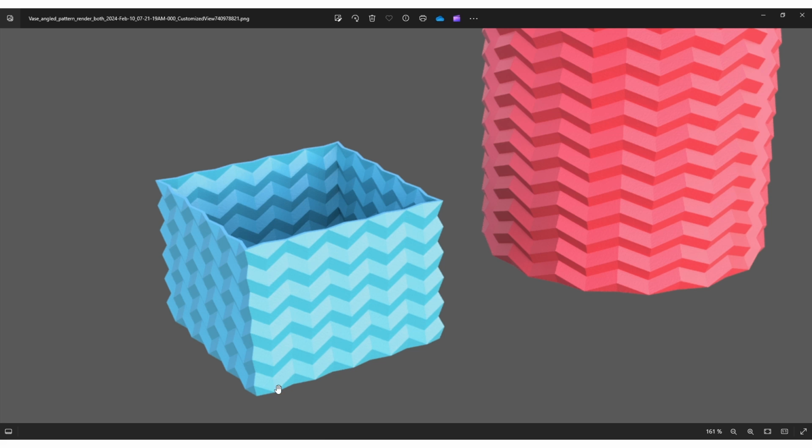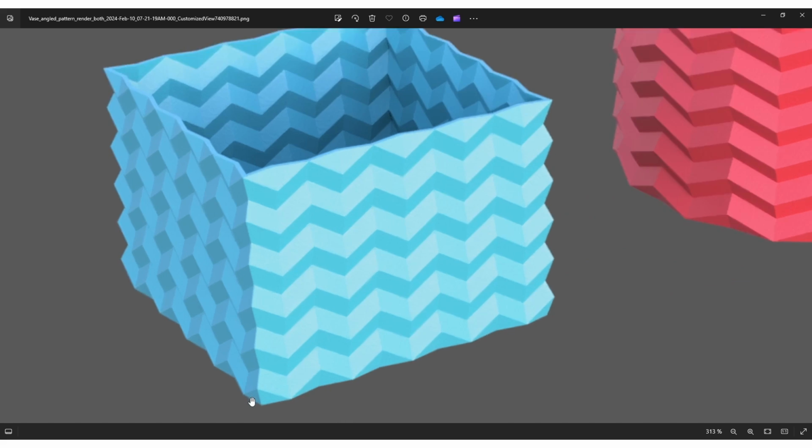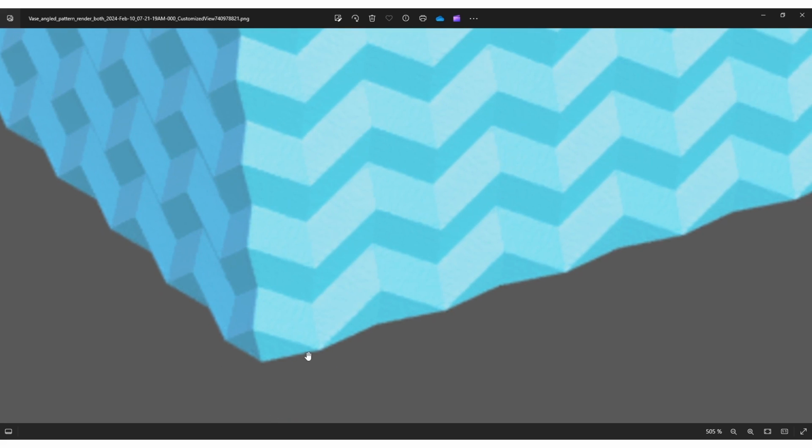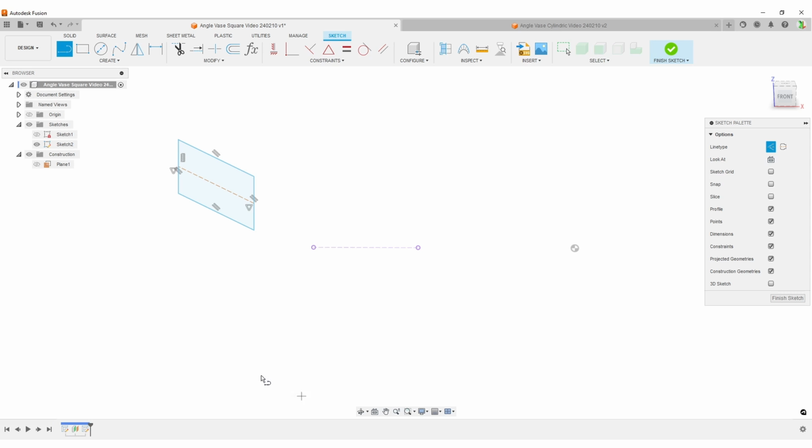Let's look at the image again. It is the full width. So this parallelogram is basically the one I made down in the corner here. It means it needs to connect to the center point of this line, and then up like that. Let's see if we can do that. We're going to make a coincident between this point here.